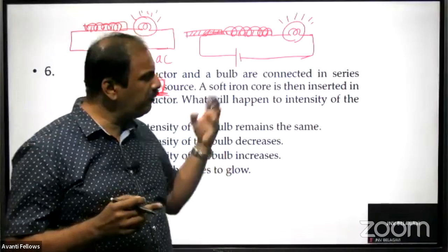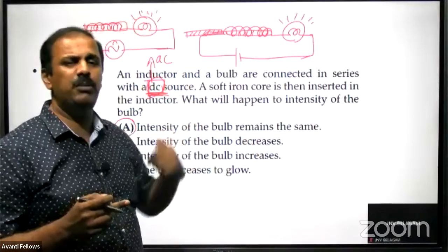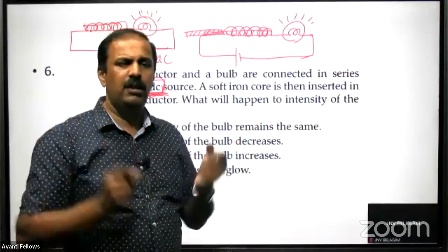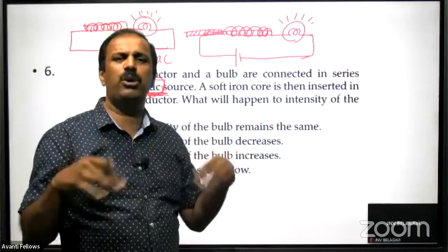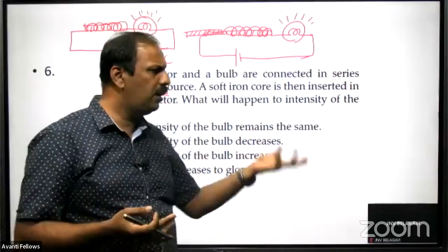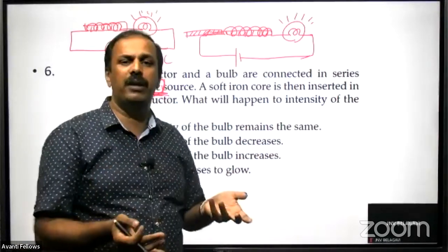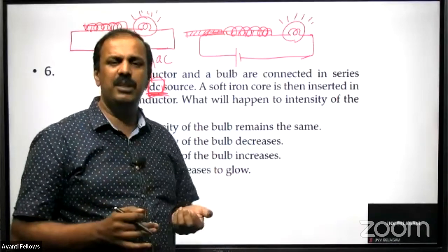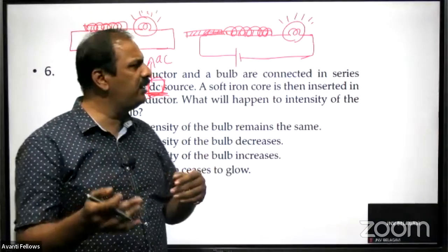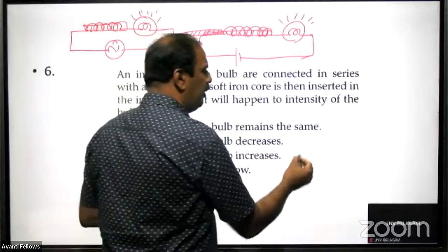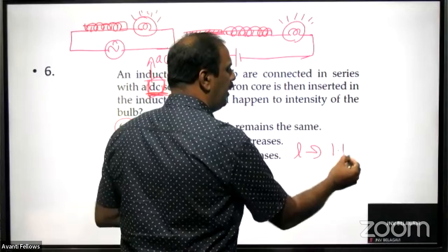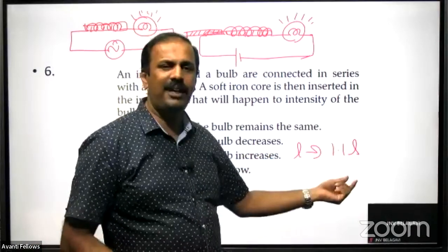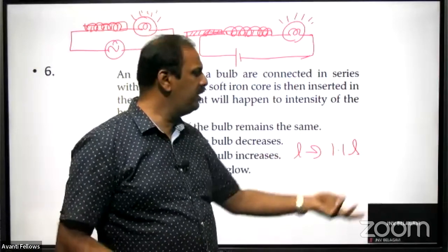Okay, so many times, even for 12th standard also, such a 1 mark question came previously. When a wire of length, something like 1 meter is taken, or the length is not given, and it is melted and made a new wire of a particular length, or 10% of the length is increased. 10% increases means previous length L will become now 1.1 L. That is 10% increase. So when it is increased n times, its resistance will change with n square times.